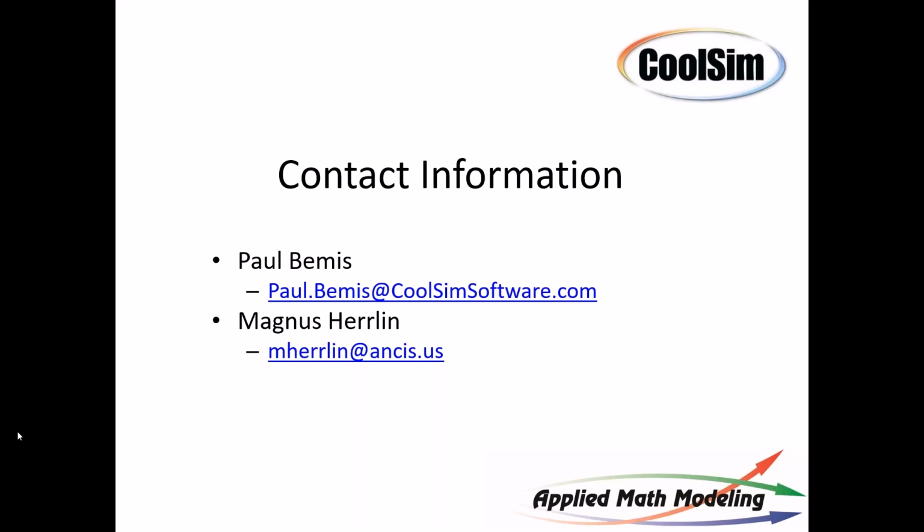The other thing about PUE is it's point in time. It changes. What you really need is the average PUE over the year, because it's not constant. But yes, you are right. If you change the cooling system to evaporative, or you add an economizer, it will change the PUE quite dramatically compared to, in this case, leakage.